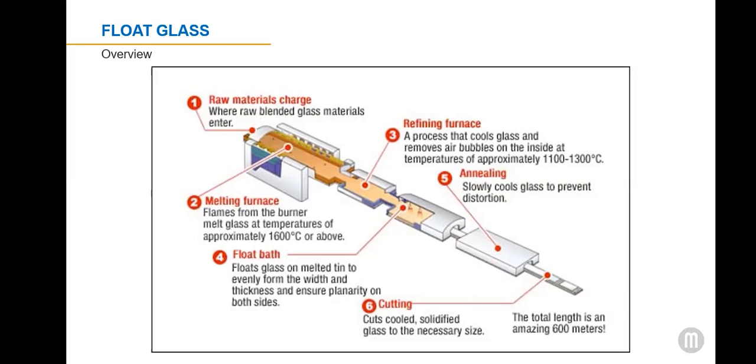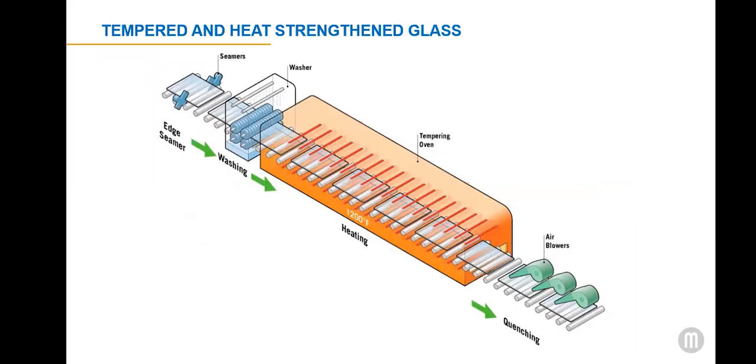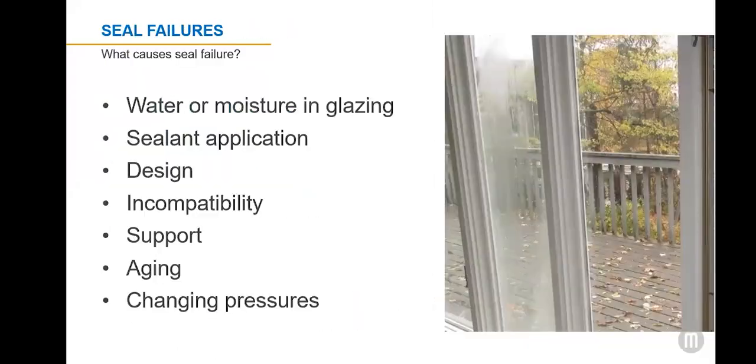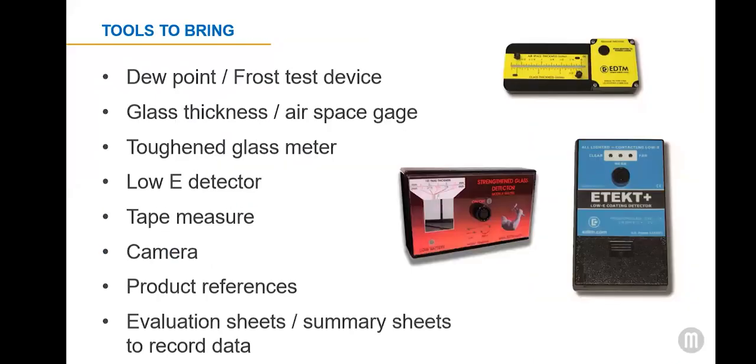One last question. Somebody asks, how can I know when a window's tempered? Most times it has a stamp that says it, which makes it easy to know, but sometimes there's no stamp. Sometimes the stamp is hidden or it's up at the top. There are tools, and I have another class that's coming up, but this strengthened glass detector is very, very accurate at determining if the glass is tempered or heat toughened, as they refer to it overseas.